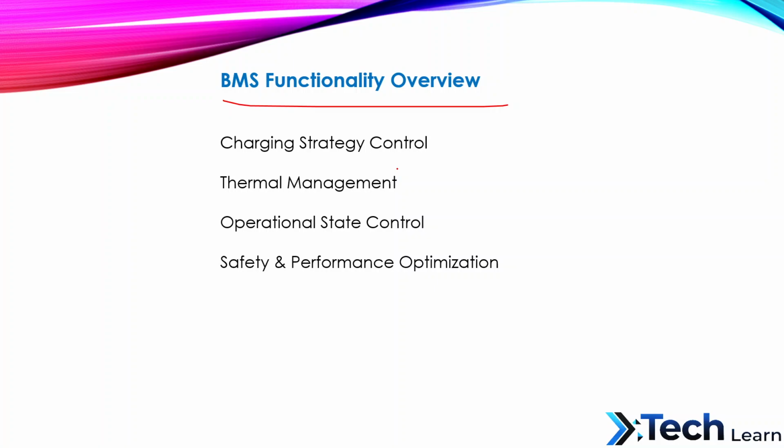A modern BMS does much more than measuring voltage and current. It performs three major functions. First, controlling charging strategy. Second, managing the thermal conditions. Third, controlling the operational states through structured logic. All of this is done to ensure safety, optimize the performance, and maximize the battery life.